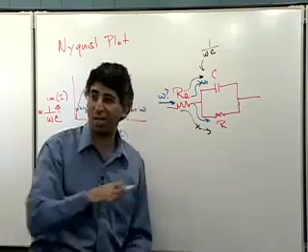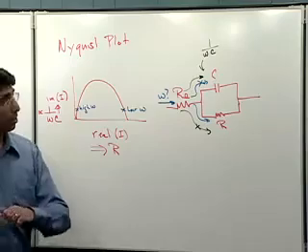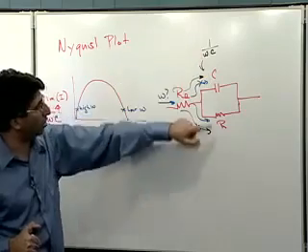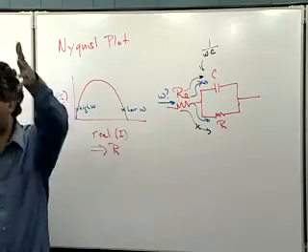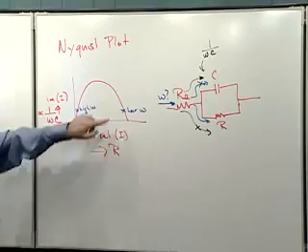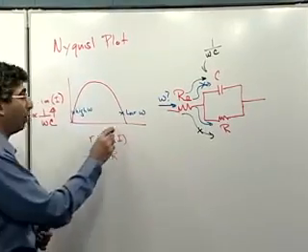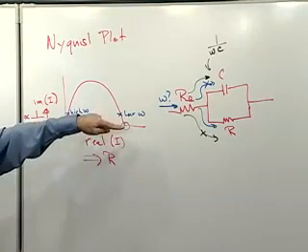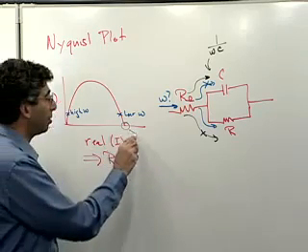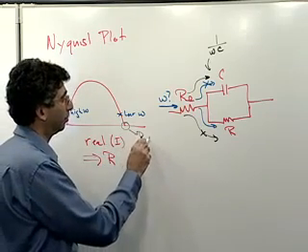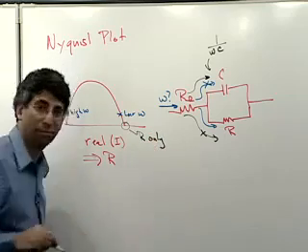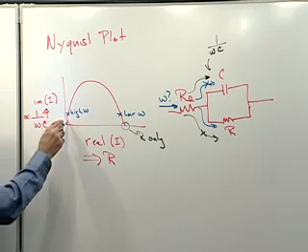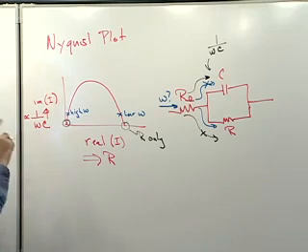And of course, there's a set of frequencies that are involved here where C, or 1 over omega C, and R are pretty comparable, and I have current going through both of those. So at this end, right here, 0 frequency, everything's going through the resistor. And then as I go to higher and higher frequency, I get to a point where everything's going through the capacitor.